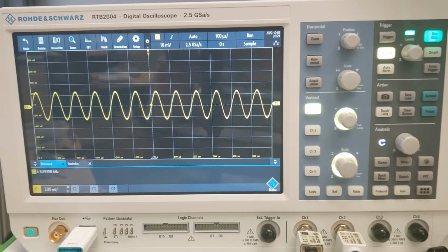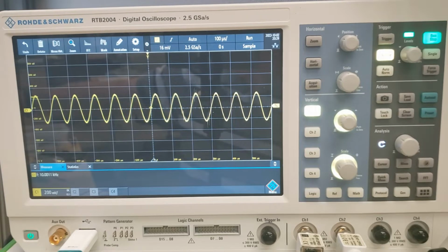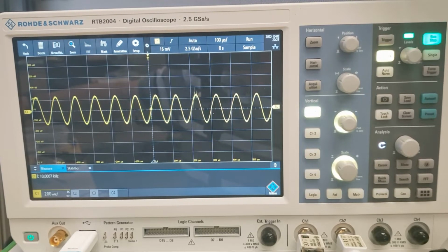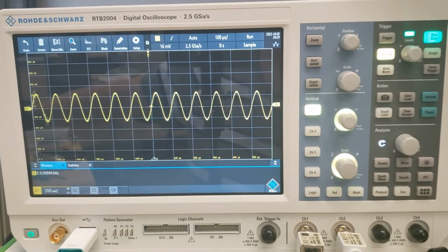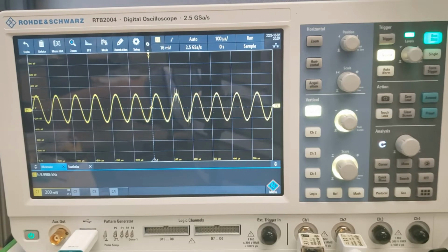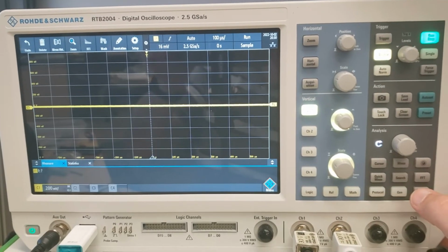Just a second. I seem to be getting a lot of noise here, and this is connected from the Keysight Edu 33211A waveform generator, which is a 20 megahertz generator. So I'm going to see if I connect it to the auxiliary out generator on the scope, whether I get a better trace. So let's try that.